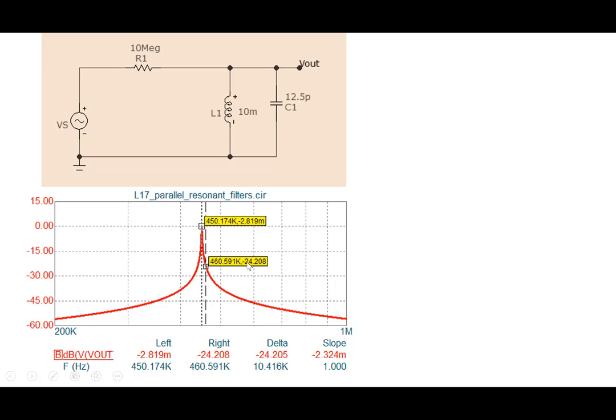So note that we are able to obtain that very high attenuation that we were looking at, 2000 dB per decade kind of an attenuation, using a very simple circuit with only an L, a C, and an R, right? With a very simple circuit, we are able to obtain very high selectivity. And the reason we are able to do it is because the circuit is based on the concept of resonance. The circuit has a natural frequency, and if the input matches the natural frequency, then the output responds very well, while anything which is away from the natural frequency, the system doesn't respond.